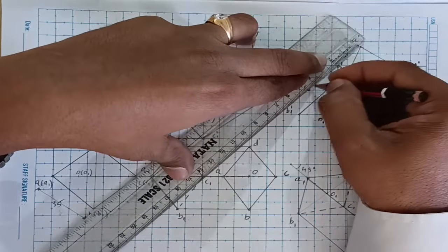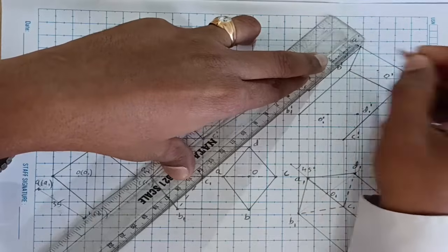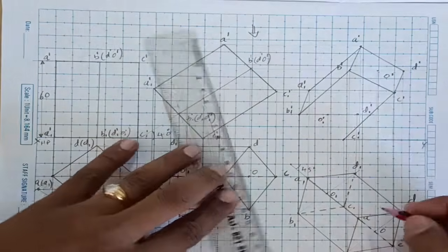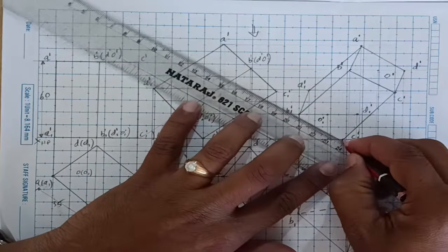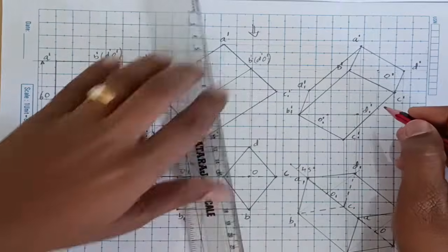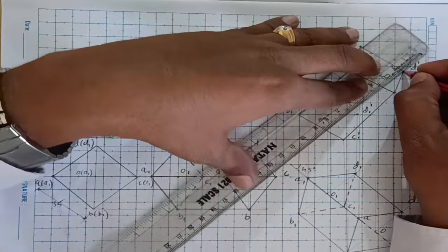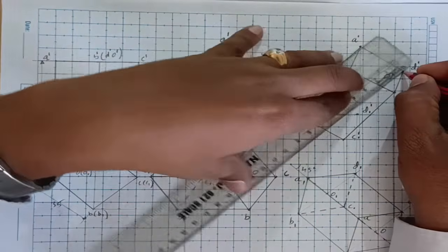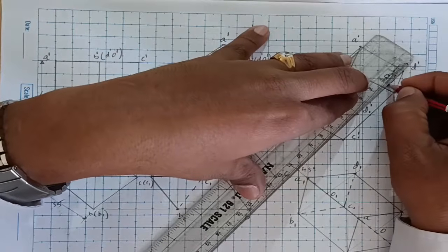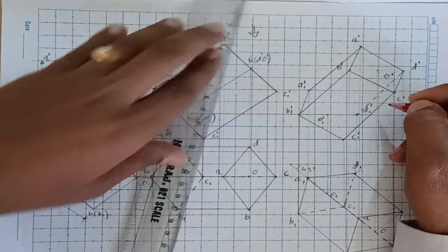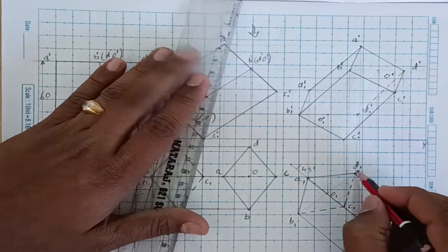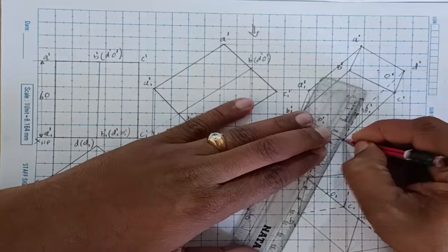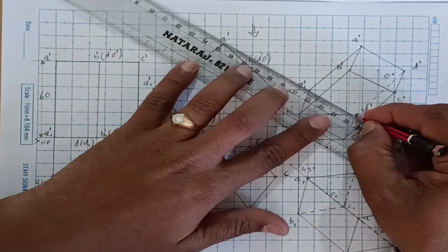I am joining A to A1, and when I am joining it is coming outside, so it will be visible. And then you finish the outer frame, that is A dash to B1 dash, A1 dash to B1 dash and then C1 dash, you can finish the outer frame. And now when I am joining D dash to D1 dash, the line is coming inside this frame, that's why this is hidden. So make this line D dash to D1 dash hidden. And now check, the endmost is D1, so whatever line comes from the D1 will be hidden, that is D1 dash to C1 dash also hidden, and D1 dash to A1 dash is also hidden.